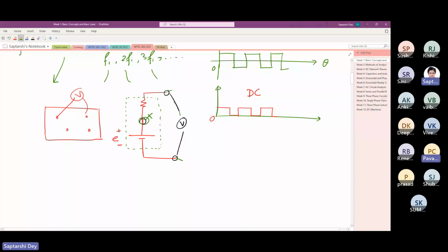Otherwise, if there is load, then the voltage will drop. The voltage that we get across the load is the battery terminal voltage that keeps changing with the load, but EMF is constant, assuming that there is no chemical change in the battery while it is supplying the load.